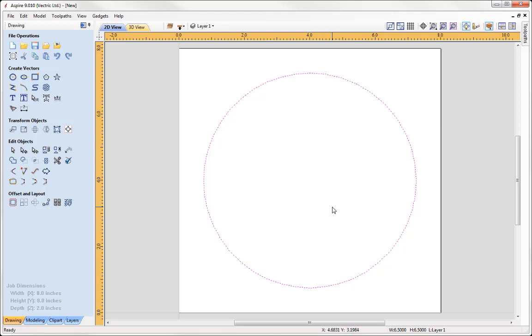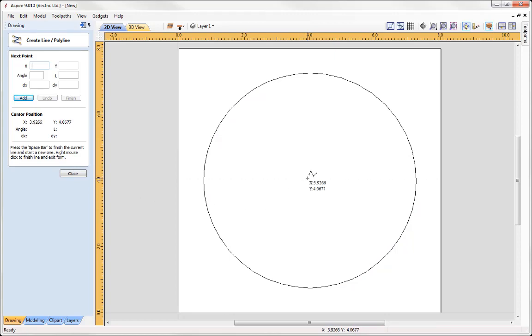So as I mentioned in the introduction, to create a spun shape we need a cross section that we spin around the left end point. So I'm going to go into the polyline tool, and we're going to draw a cross section from the centre of our job going over to the right hand side to cover the radius of the bowl that I want to make. So starting at the centre ensures that when I come to spin my part, it's going to spin that around the centre to create the shape. I'm just going to go up by 1 inch so I can see the length there is displayed as 1 inch. So I'm going to click that in place, come over to the right hand side.